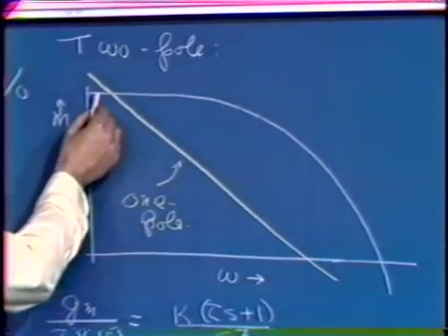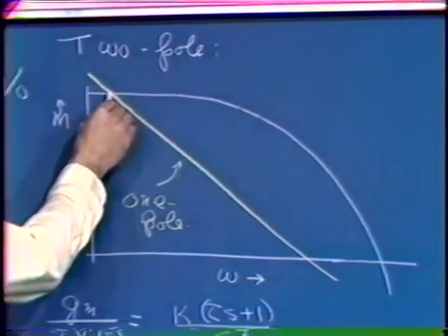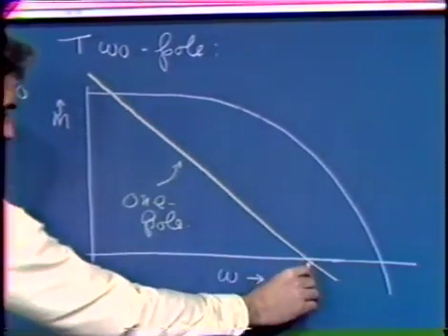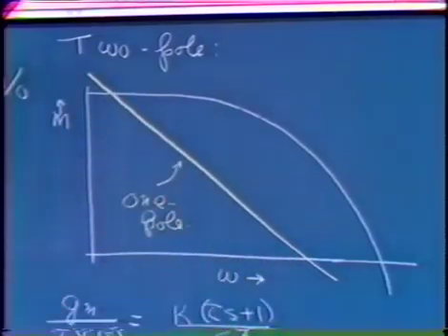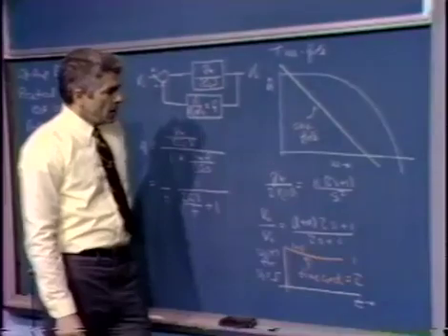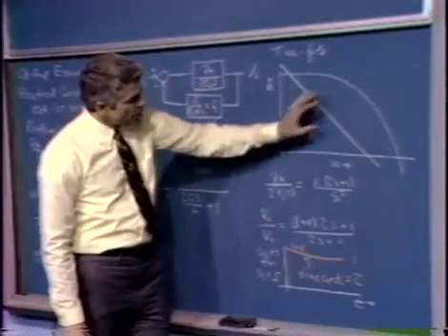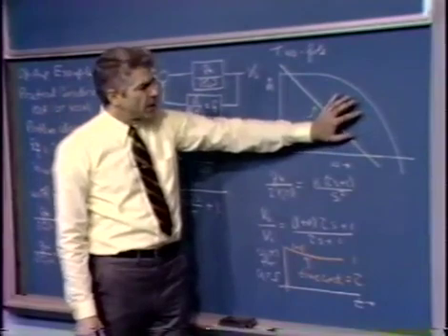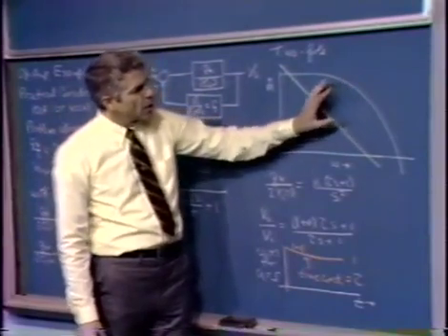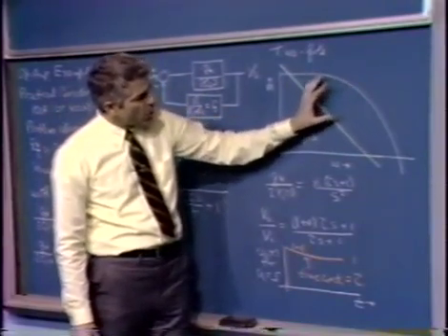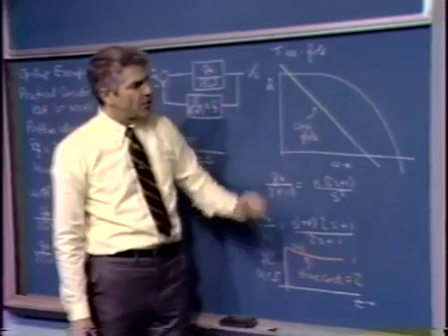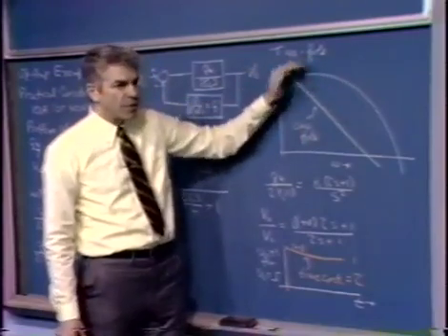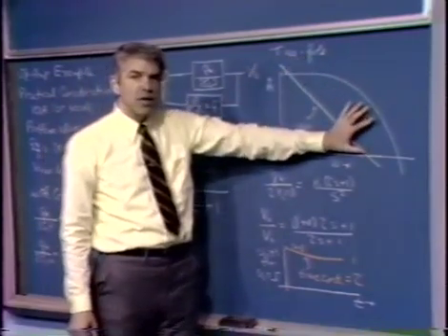Our approximation tells us that at least over from here to this frequency and possibly beyond, we'll have basically a single pole roll-off associated with the open loop transfer function of the amplifier. We might wonder, though, we're throwing away a good bit of amplifier capability. This area here represents a region where the amplifier has considerably more open loop gain potential than we're actually using. We've had to squeeze down the open loop gain over a very wide range of frequencies in order to make the amplifier stable.